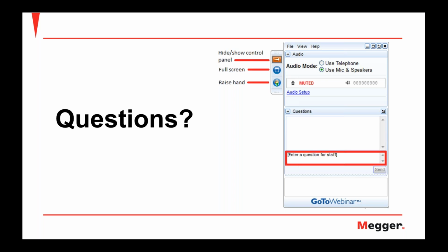A boost charge, the boost voltage, is what's used when you equalize a battery string. This is higher than the float voltage. And its purpose is that you would apply this for a given amount of time, and it helps break down the sulfation crystals within the battery that will allow you to regain some capacity of that battery.